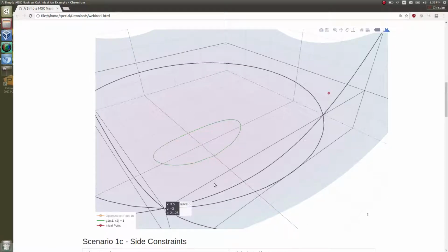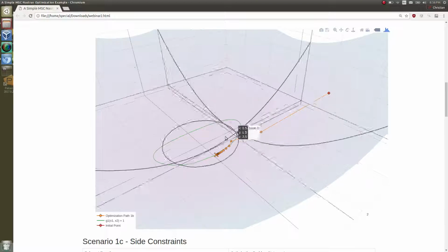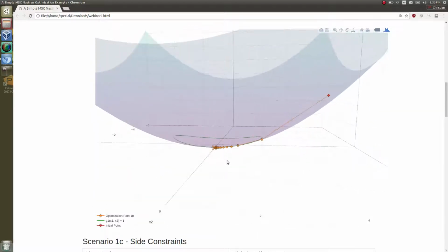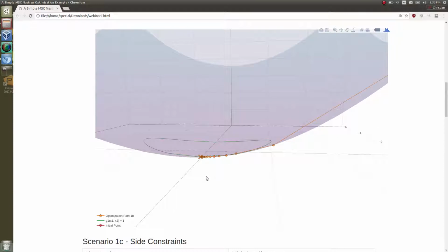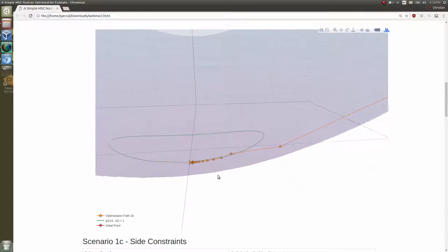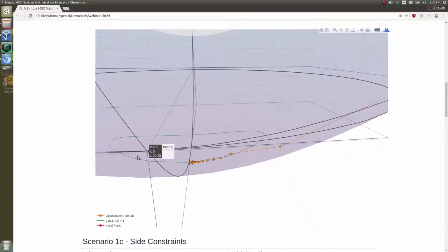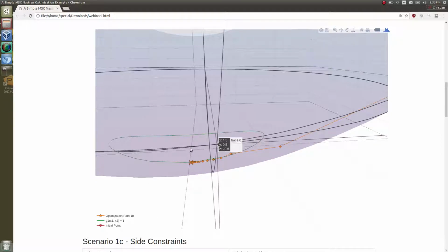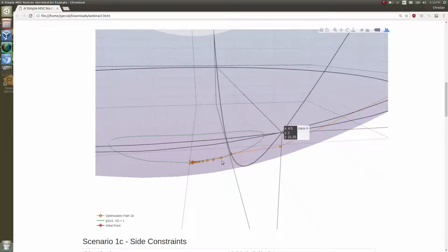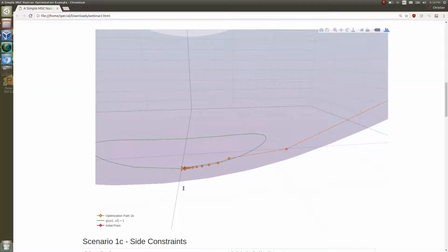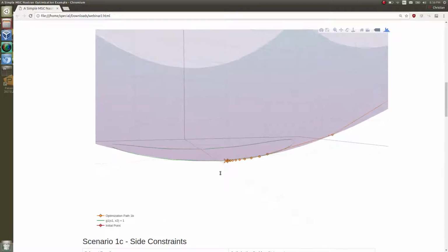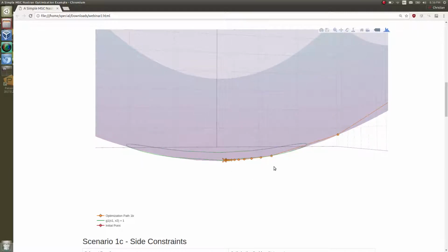During the optimization, it will make an attempt to go towards the minimum, but then it encounters the design constraint I just mentioned a moment ago. It understands that everything outside of this ellipsoid is acceptable. Anything inside is not acceptable, so that's why it remains outside of the ellipsoid. But then this is what it does. It realizes that once it hits the constraint, there is still opportunity to further minimize the objective function. So you see it move along the constraint towards the minimum here.